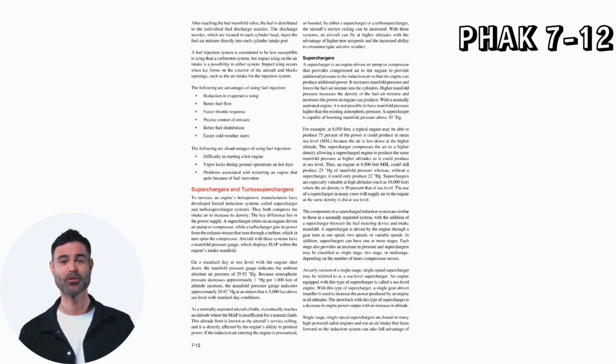The components in a supercharged induction system are similar to those in a normally aspirated system, with the addition of a supercharger between the fuel metering device and intake manifold. A supercharger is driven by the engine through a gear train at 1 speed, 2 speeds, or variable speeds. In addition, superchargers can have one or more stages. Each stage also provides an increase in pressure, and superchargers may be classified as single-stage, two-stage, or multi-stage, depending on the number of times compression occurs.